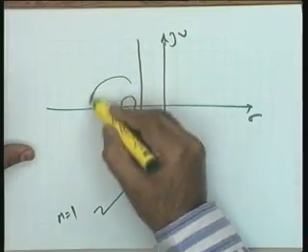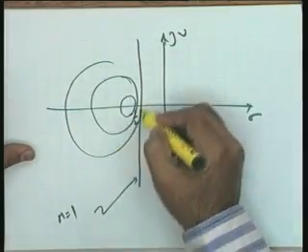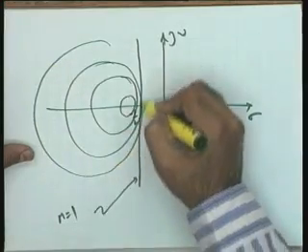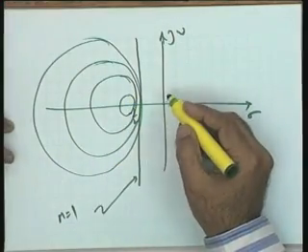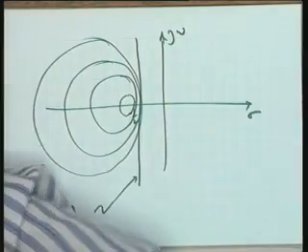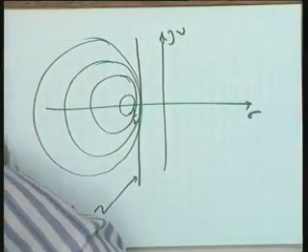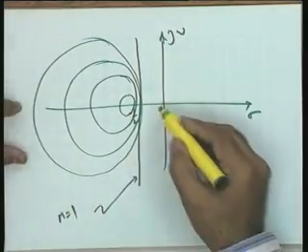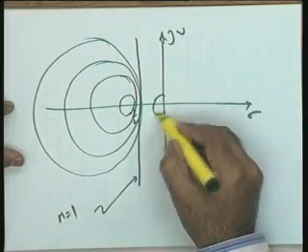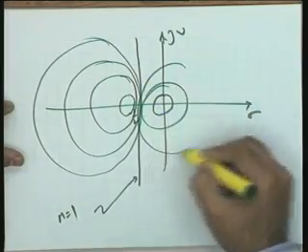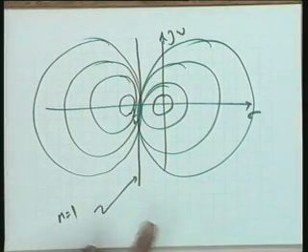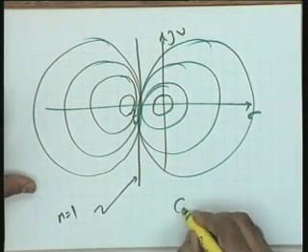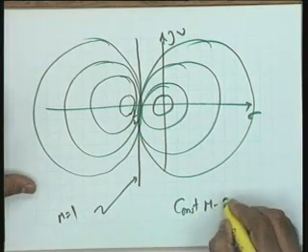Let me make other cases by writing that equation for different values of M. On the other side, the sketch is going to be of the following nature. Yes, I think I can roughly give you this sketch. These are the M circles, as they are called in the literature, constant M circles.